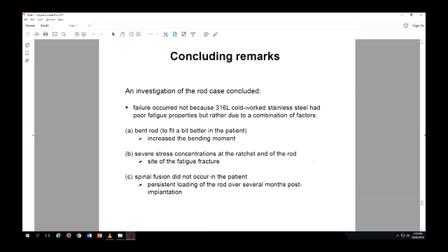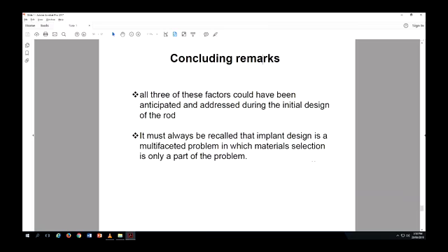So if it wasn't bent and there wasn't much bending or cyclic loading, for that compression or tensile strength, it would have been enough, right? Whereas for this particular thing that they didn't predict, it wasn't strong enough in terms of fatigue properties. And they didn't know that because it just simply wasn't designed for this purpose, right? So it's important that you look at the strength, the material that you're choosing, and also look at the design.